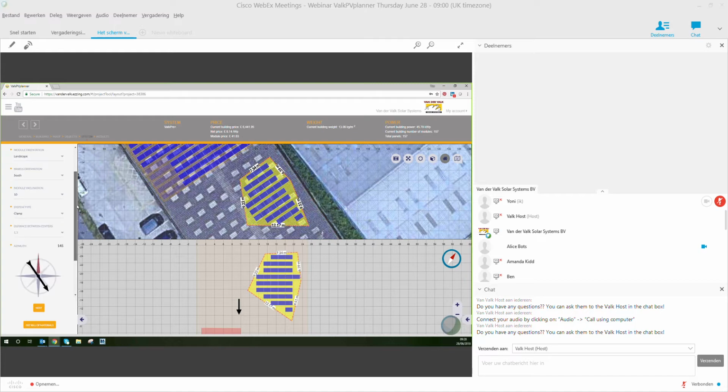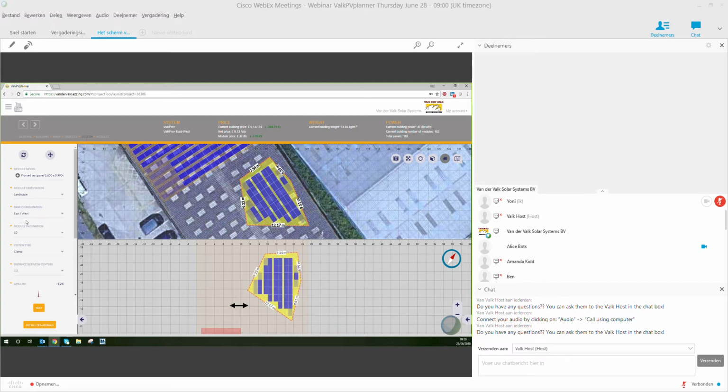Let's say that's our next sub area, and when we finish, it will fill that sub area with panels. Maybe on this particular one we want a east-west system. Refresh, really max that out with the maximum number of panels that we can fit. We might take out these ones. These are half peaks. These are possible in the system. You'll automatically have back plates and shorter carrier profiles added for those, but maybe you just want a nice neat looking system, something like that.